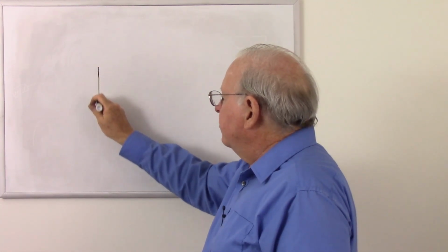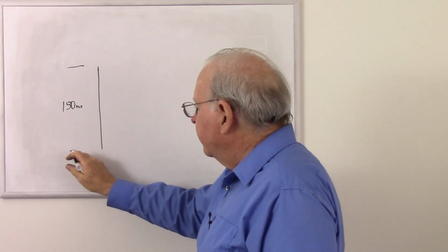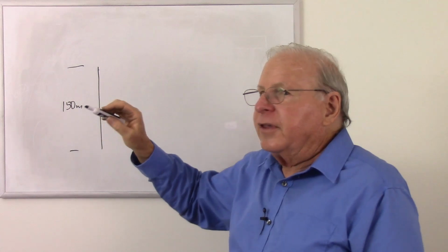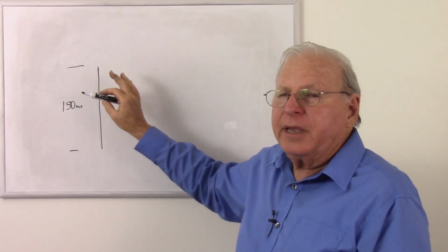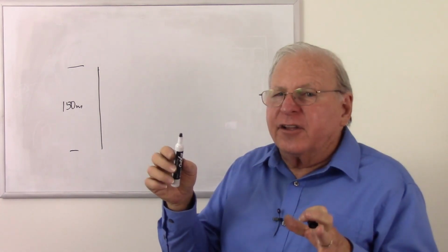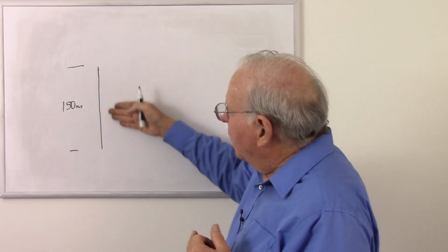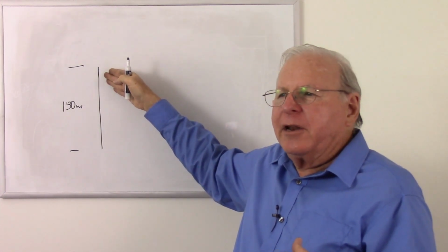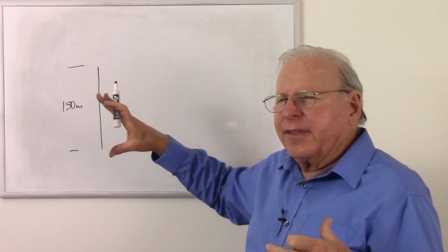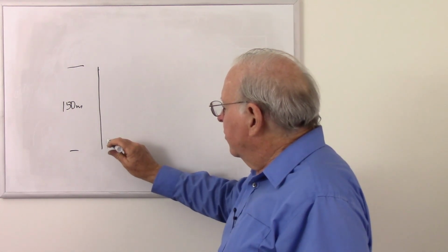So we're making an assumption here that at 150 meters, the length of this wire, these electrons are traveling at the speed of light. Of course they're not. The wave of energy is traveling close to the speed of light, but not quite. And so in reality, antennas are physically shorter than electrical length. So if this was a real antenna, it would be a little shorter than 150 meters, but we're going to assume that this wave is going back and forth in this wire at the speed of light rather than something like 95% in reality.